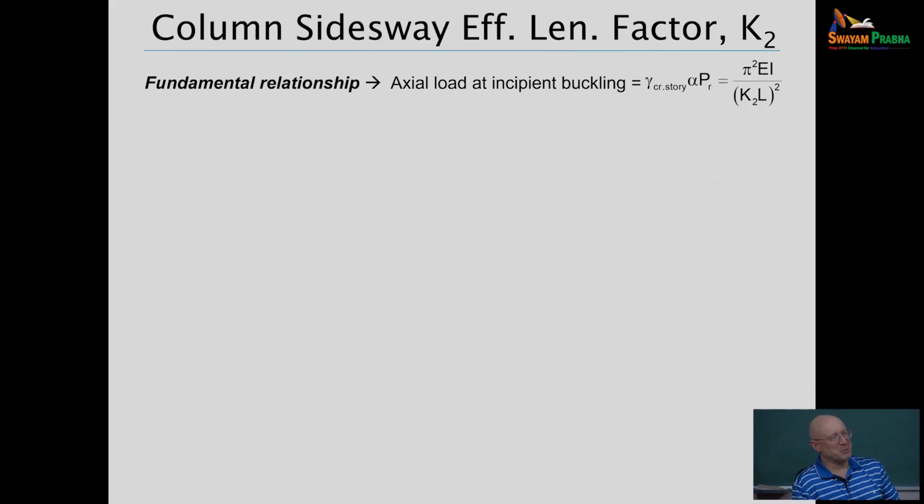All right, we talked about the effective length factor K1 for non-sway yesterday. And again, remember, I emphasized at the beginning of class today that you don't need the K factor. You just need the axial force in the member at incipient buckling when you design from that. So if you're using computations, you can work straight from that. But you still may want to calculate a K factor because it helps you understand what's going on, right?